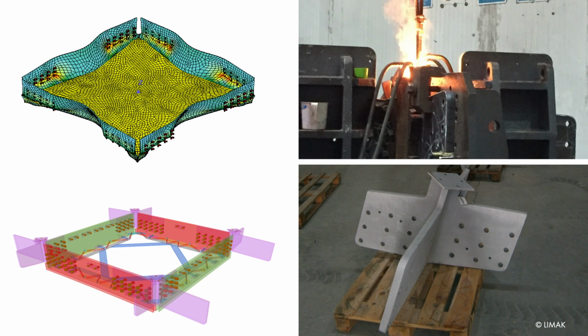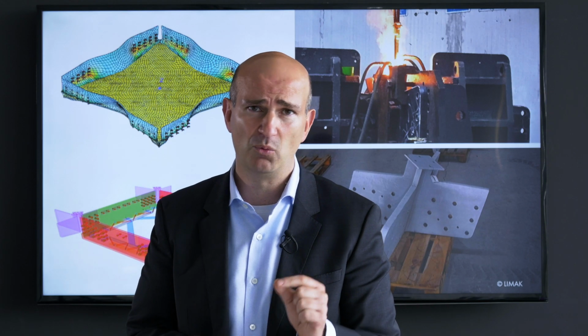And the challenging part of that was to generate the engineering by means of scripting. So there have not been single checks, but there have been custom master systems, and out of that then a very detailed model for every single cassette could be generated, as can be seen in the images. And the fabrication behind it, so the use of innovative welding technologies, for instance, for the cross elements, has allowed us to reach a very high degree of precision. Just to have an idea, we are talking about less than 1 millimeter out of a surface which covers 10 square meters.